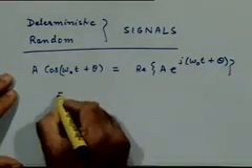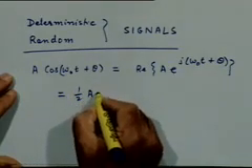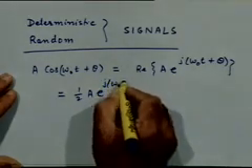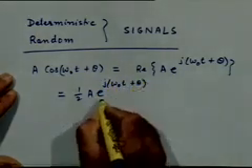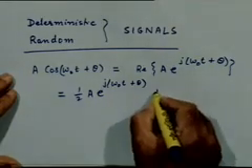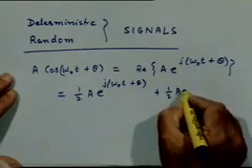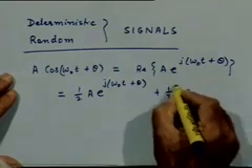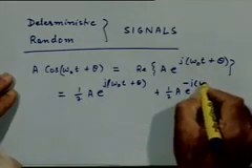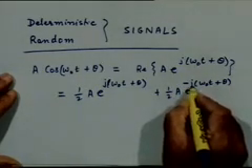Now this is very basic stuff, but it is useful to review this because sometimes people forget the basic stuff and they have difficulties later. So this is, let's say, the phasor which is rotating in the clockwise direction. If it is clockwise, then this is the sum of these two phasors, the other one rotating in the anti-clockwise direction, as indicated by this negative sign in the exponent.